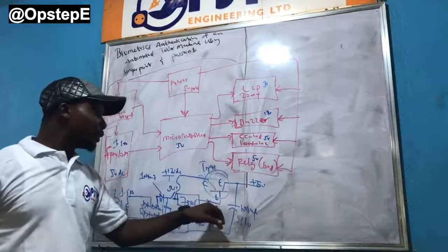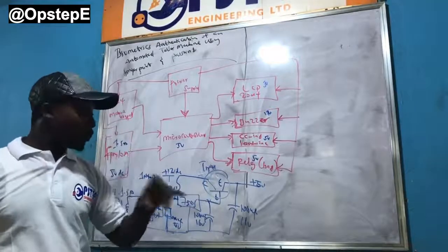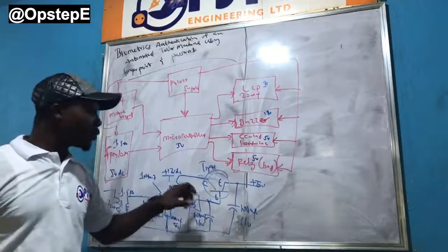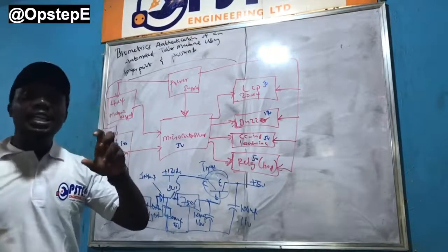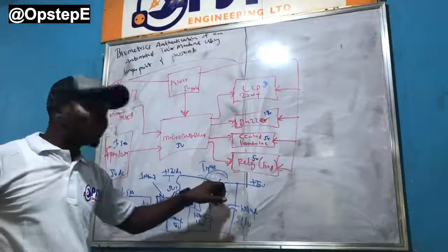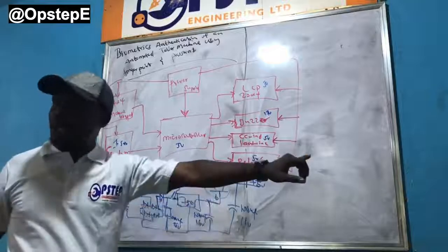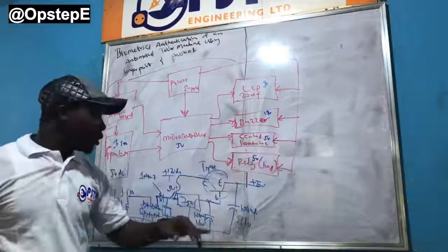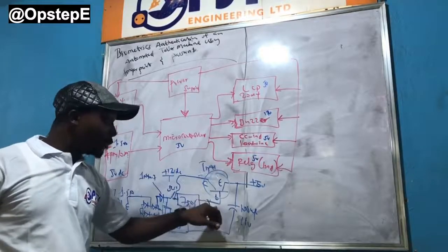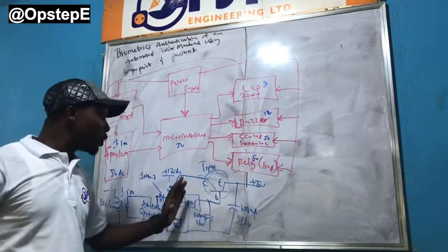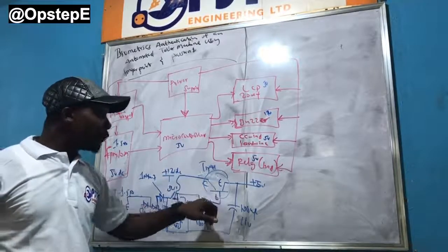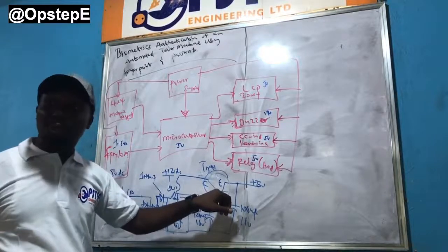Now what happens is this. We put a resistor here and calculate to a certain point where this transistor is the one that is supplying the current. It is when the current overshoots that setup that this transistor turns on and begins to produce the excess. We can say, since this guy can produce 1 amp, let's set a resistor that allows it to only supply 500 milliamp. So at 500 milliamp, the voltage at the base of this transistor will not be enough to turn it on.